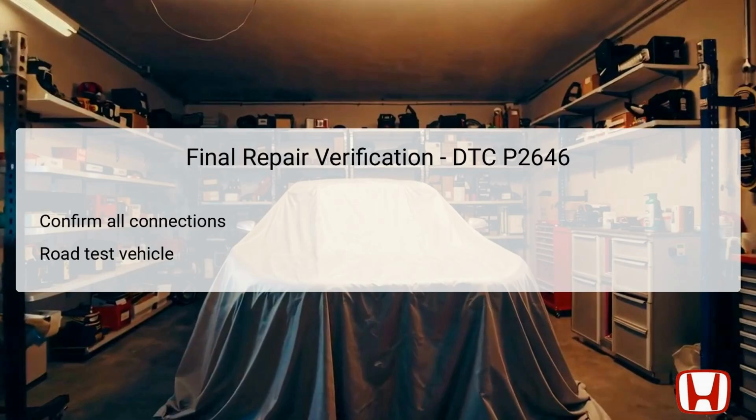Following this, a comprehensive road test should be performed. Driving the vehicle under various conditions helps confirm that the VTEC system is functioning correctly and that the DTC P2646 does not reappear. It is vital during this stage to check for any return of symptoms related to poor performance or the illumination of the check engine light. This final phase ensures that the repair was successful, contributing to the continued reliable operation of the vehicle.